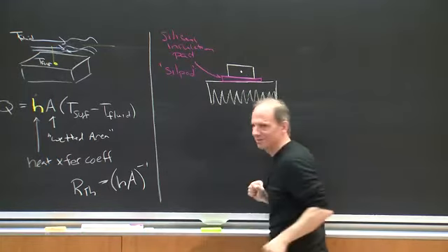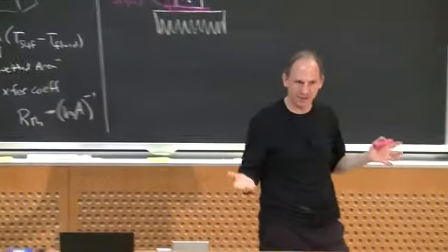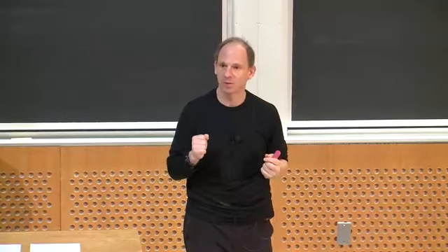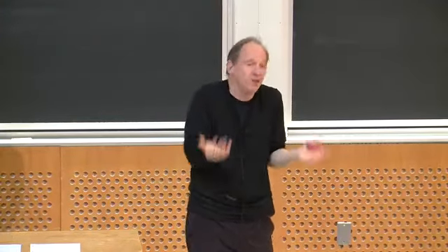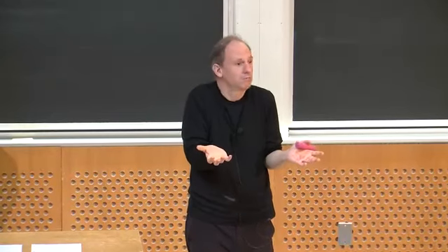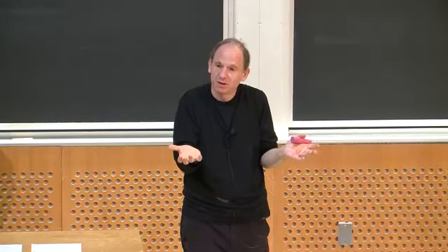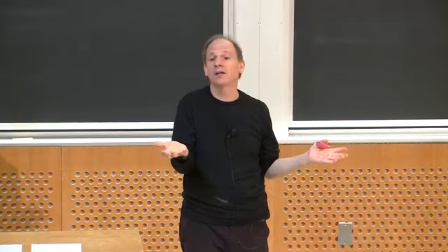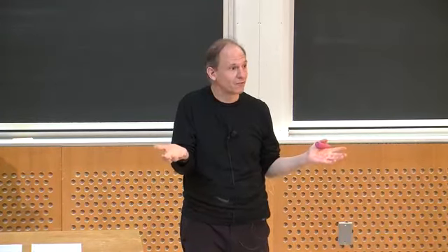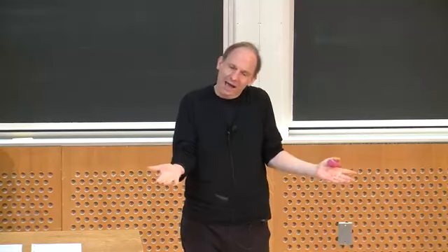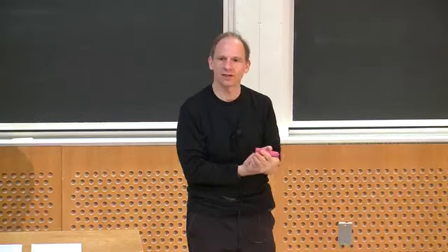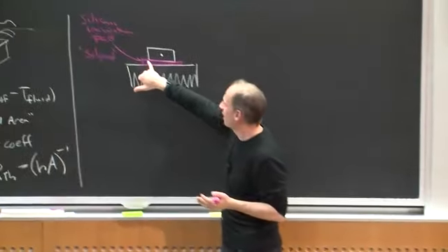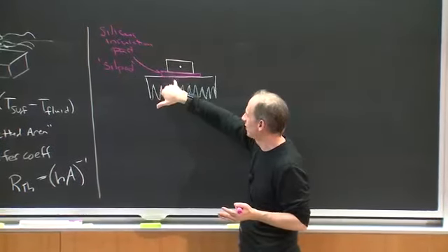That's Bergquist's trade name for it. There's a lot of companies that make it, and they come in varying degrees of quality and electrical insulation capability and so forth, okay? In some applications, maybe you don't need electrical insulation, right? If you happen to have a package that was already electrically insulated, and they do make some FETs that way, or the package happened to be connected to ground, maybe you could connect that directly down to the heat sink, okay? But often, you will have some other interface between your device and your heat sink.